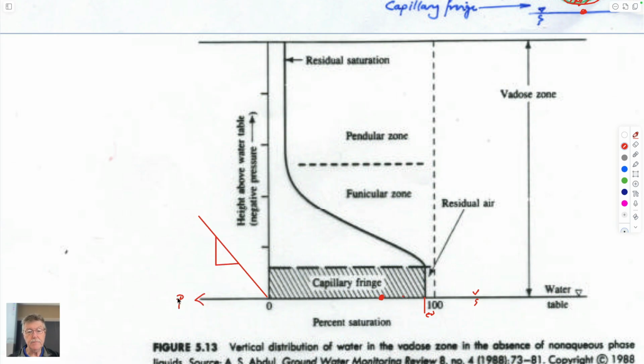This would be pressure, this would be 1, this is a unit weight of water, and this would be elevation. And we'd expect to see within here the different components. So this is waiting for air to break in through here. Air is the non-wetting fluid. So this would be the saturation of the non-wetting. And this would be the saturation of the wetting, the water that's left in it.